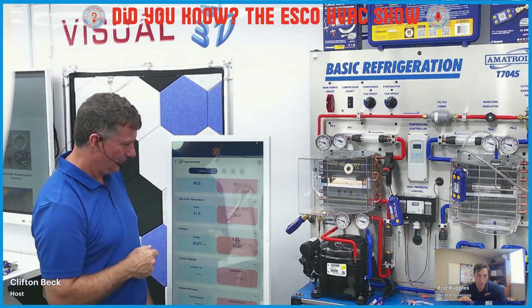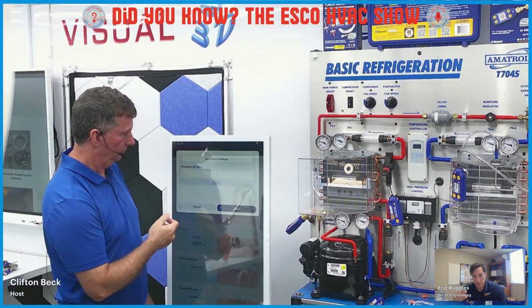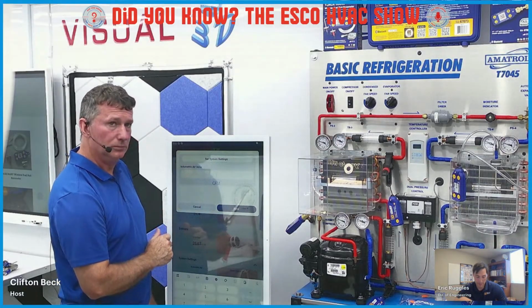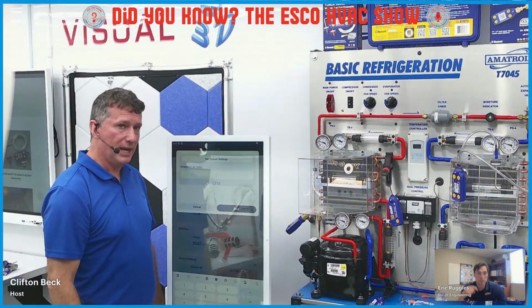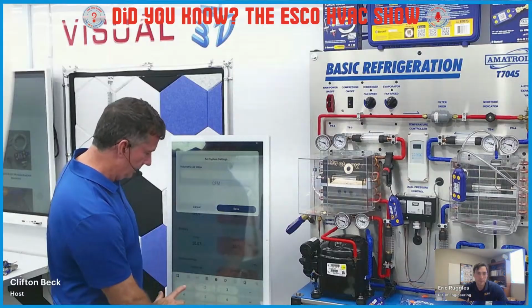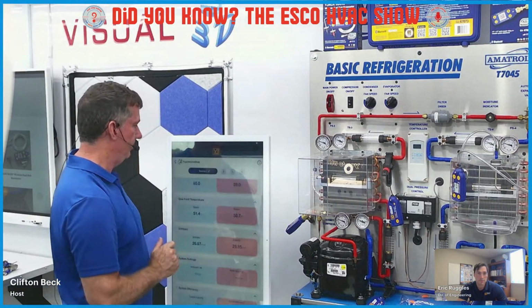So if you put in the volumetric air, if you click on that blue box, you can either input the volume of air that the fan's supposed to be doing, or if you use your anemometer, it'll show the last 3 anemometer readings. No kidding. Actual, true calculated airflow then. All right. Nice. So we'll just pick a random number on this one.